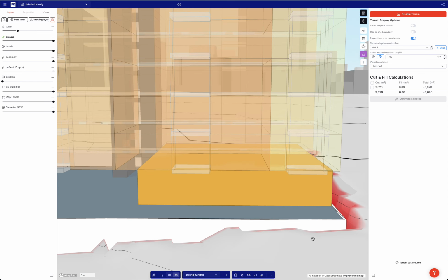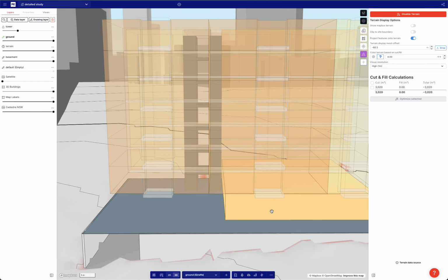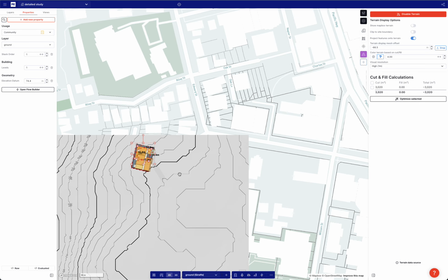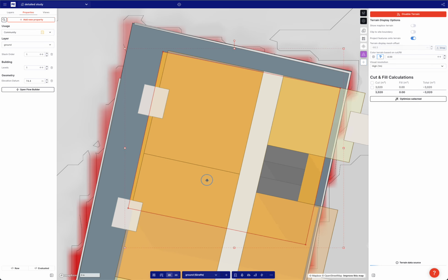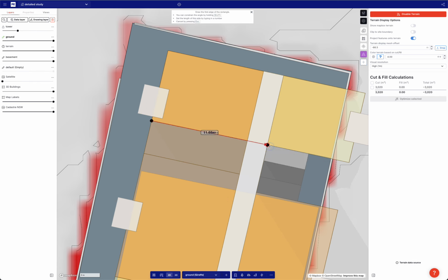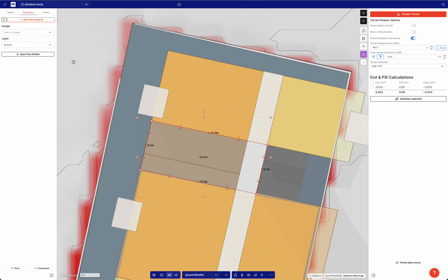There you'll see that. And now what I'll do is I'll drag out a ground floor apartment over here. Shift F, just zoom straight to. And I'll do that, and it can go over here. And then we'll draw a rectangle like this, and this will be the lobby.